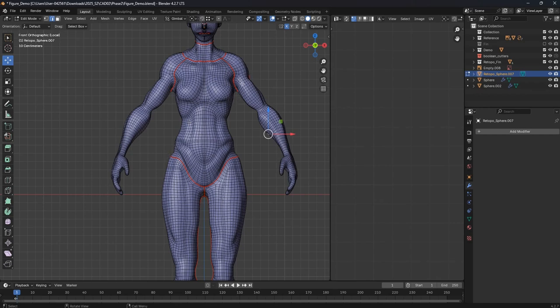And remember, right now you are going to unwrap the UV map. It's just like an origami. You are going to unwrap this model and flatten it. So if the model looks like a cylinder, there's supposed to be a vertical cutting edge in the middle, so that you can use the edge to flatten your model. So please remember this principle.